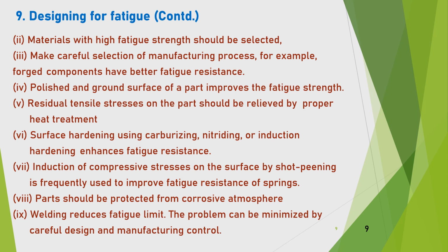Materials with high fatigue strength should be selected. Make careful selection of manufacturing processes. For example, forged components have better fatigue resistance. Polished and ground surface of a part improves the fatigue strength. Residual tensile stresses on the part should be relieved by proper heat treatment.